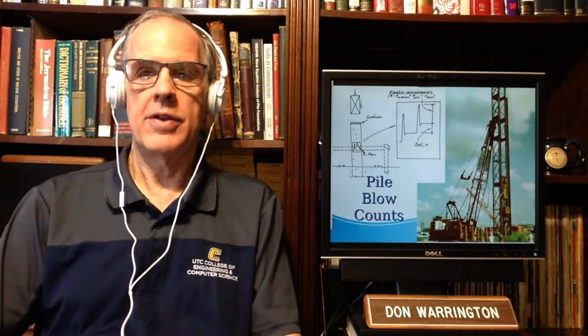You've got three. You've got energy that is stored in the pile, which compresses the pile. The second is energy that is stored in the soil elastically. And three, energy which is dissipated into the soil, either from plastic or from dynamic effects.